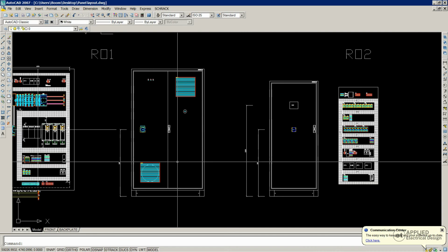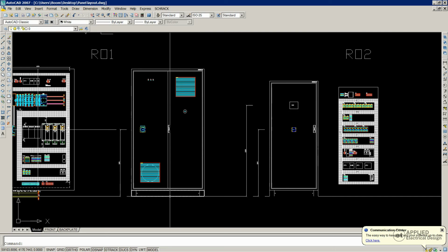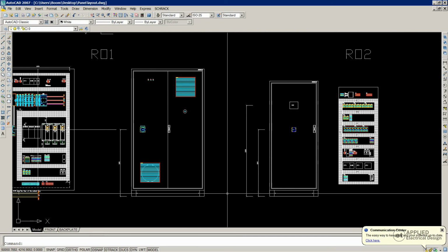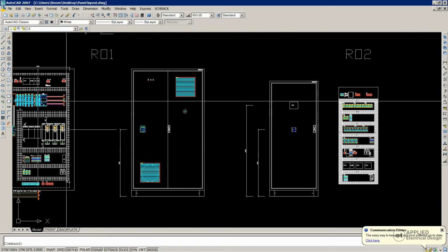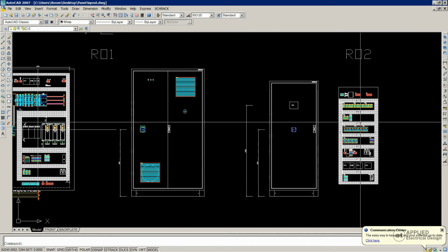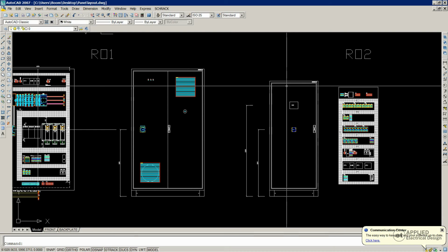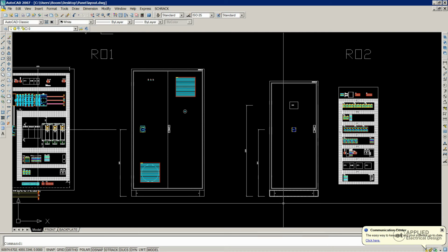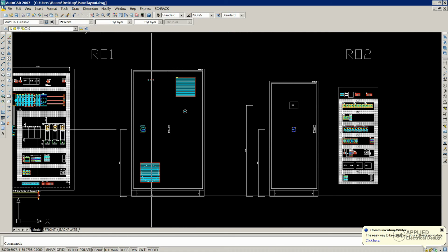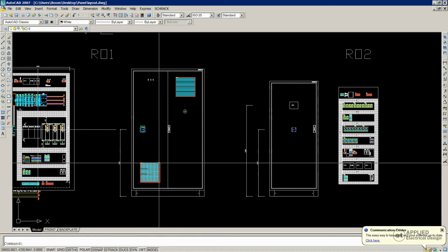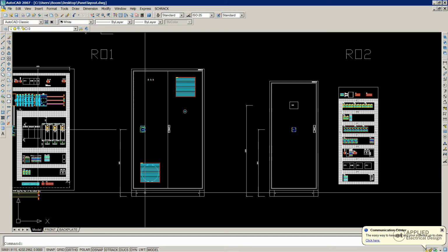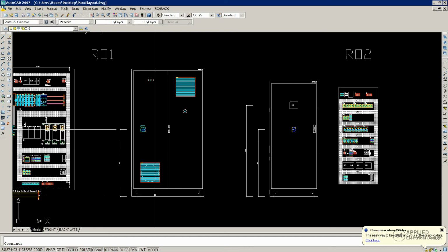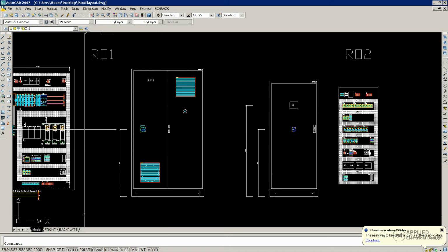And then these two would be an example of a freestanding enclosure. So just one field, one enclosure, and with all the equipment inside. Over here also, this one is in height of 1800 millimeters with the base of 100, and also in this case this is a 2000 in height for the enclosure, and then additional 100 millimeters for the base. We're gonna talk about the accessories and the base and everything else later on in the course. For now, just an example.